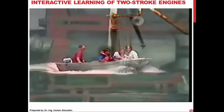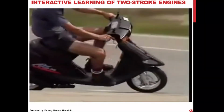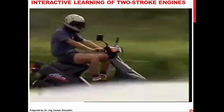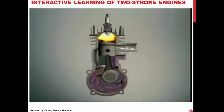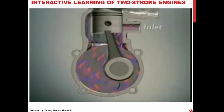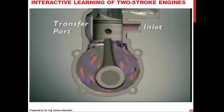In a two-stroke engine, the inlet and exhaust ports are opened and closed by the movement of the piston. But it is still an internal combustion engine and has the 5 events common to all such engines. Intake occurs when the air-fuel mixture enters the crankcase. It's then transferred from the crankcase to above the piston.